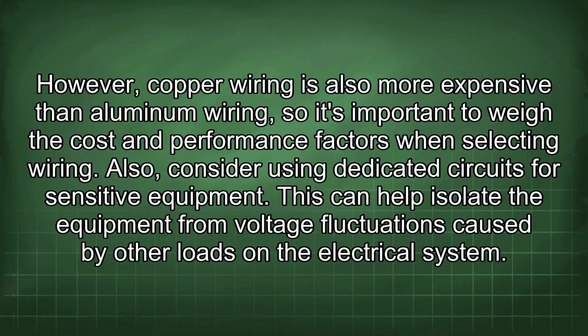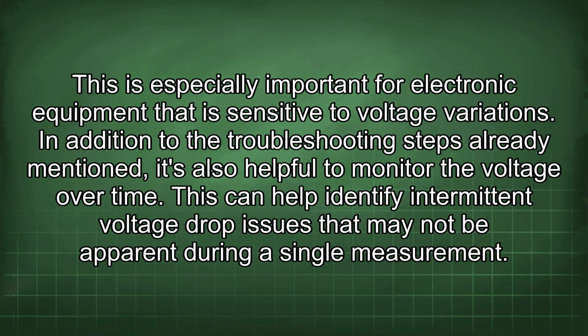Also, consider using dedicated circuits for sensitive equipment. This can help isolate the equipment from voltage fluctuations caused by other loads in the electrical system. This is especially important for electronic equipment that is sensitive to voltage variations.